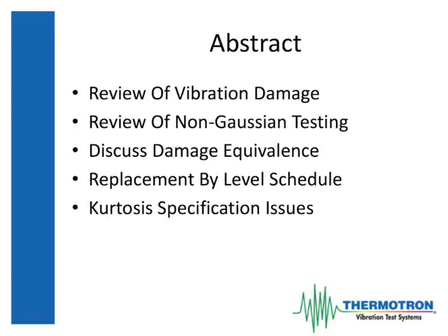I'm going to make some very broad claims about damage equivalence, and so I want to stop and take a moment to discuss what that means. Then I want to jump into how you might replace a kurtotic test, giving a very simple example about ways you can run tests on your shaker faster than using kurtosis. And then finally, I want to get into a number of issues that we've found as we developed our kurtosis algorithm, using it in specifications and problems with running it specifically on an electrodynamic shaker.